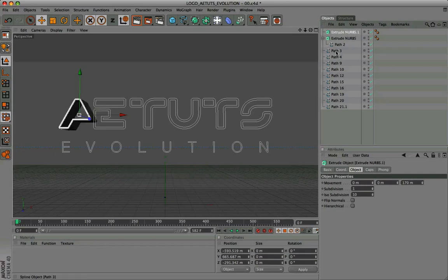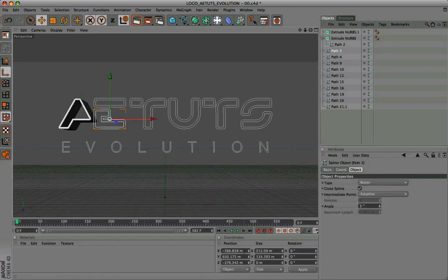As we apply it on a new path, in this case the lower part of the E, we have to change the pivot of the extrusion before entering the path. Let's use the change pivot tool. Copy and paste the coordinates into the duplicate extrusion.